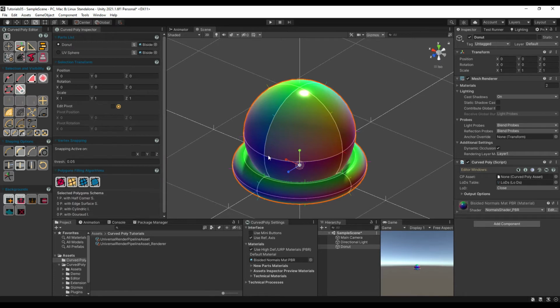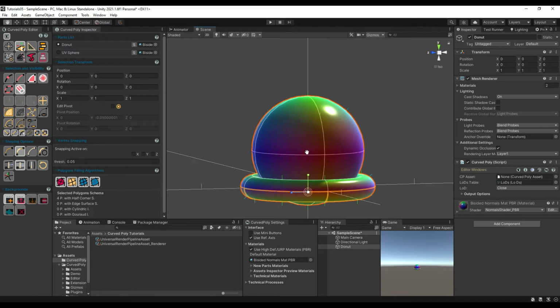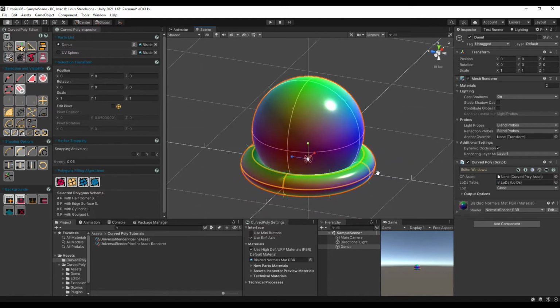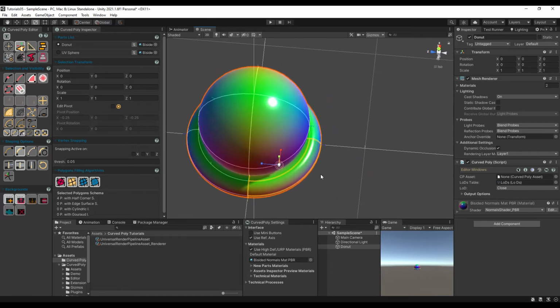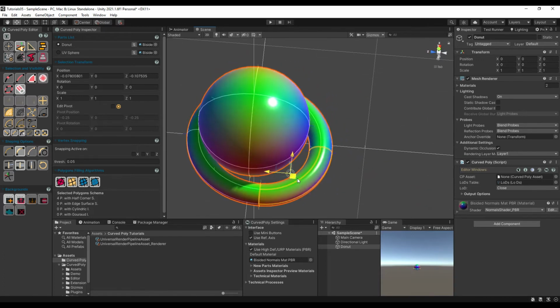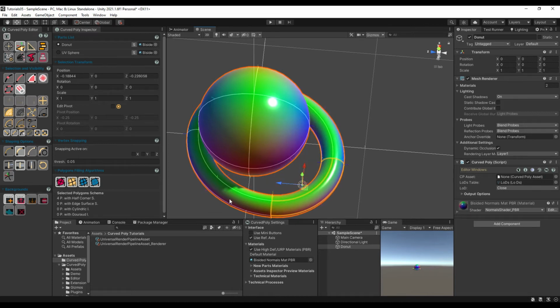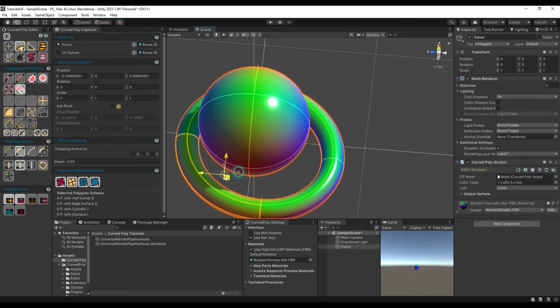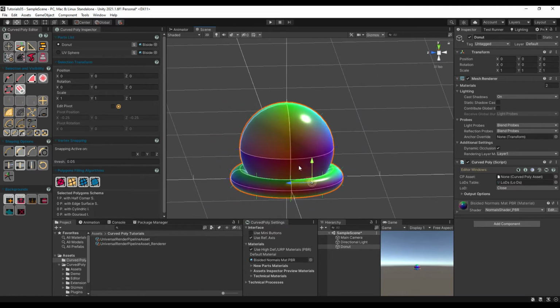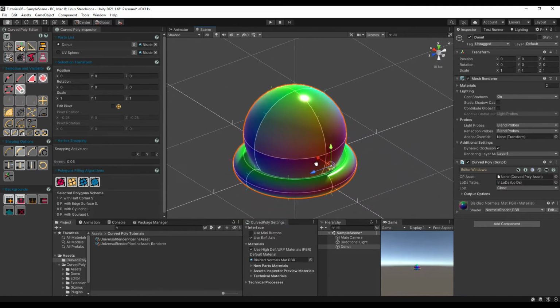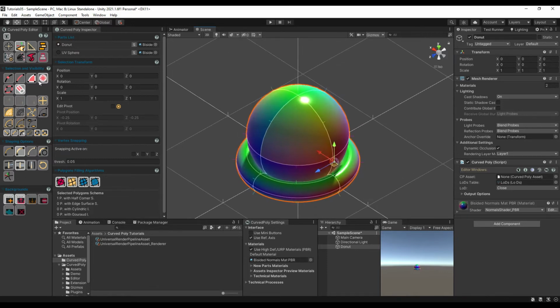Opposite to the loop is the ring. A ring is a chain of polygons. In order to pick a ring, we need to select an edge, and the polygons attached to that edge will be selected first, then the chain is propagated to more polygons if possible. The condition here for 2 polygons being chained is to have a common edge. The chain is propagated only on curved quads, through opposite edges, and stops if any polygon is found not being a quad, like a curved triangle. Depending on the edge you start with, the ring may be closed or open as well.